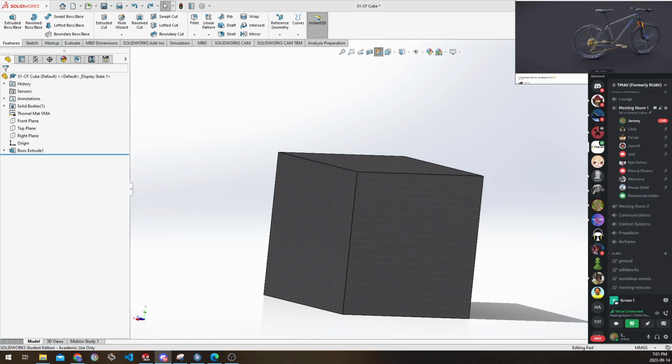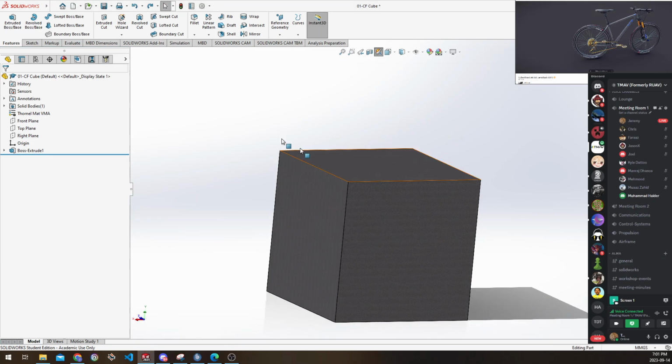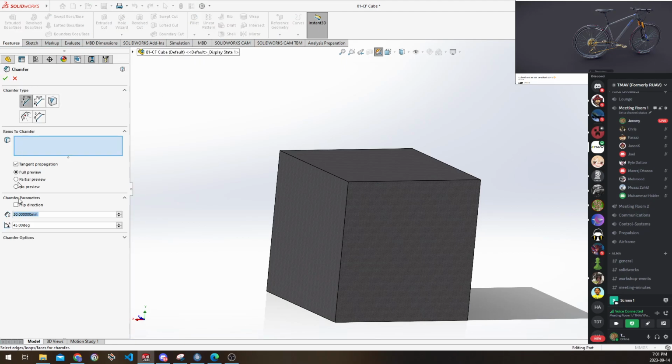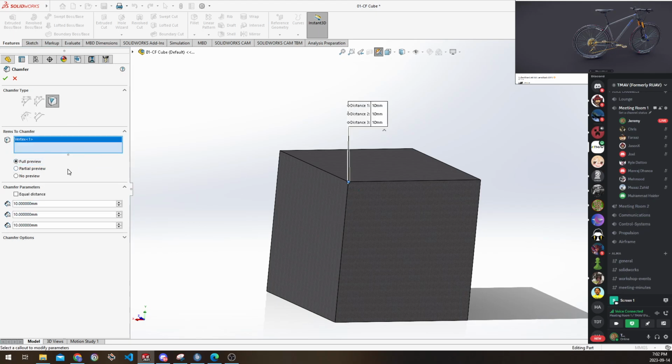Jeremy, sorry. Yep, no worries. So I couldn't see the asymmetrical and symmetrical option when I was doing the chamfer. Yep, so when you go to the chamfer tool, at the top here, right? So right now you shouldn't see it at the bottom. There's an angle option. So if you wanted to force, for example, that 3-degree angle I'm talking about, you could do that here. But the asymmetrical is in these options up here. So you see right now, we're doing angle distance. That's the chamfer type. We want to do distance. That will give us our asymmetry. You can also do a distance across the face, offset face, and there's also a vertex one, right? So this one's also pretty cool.